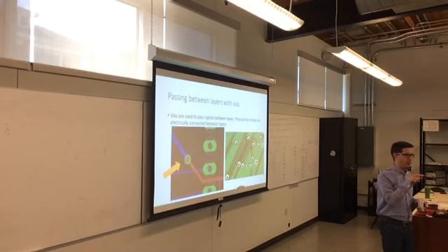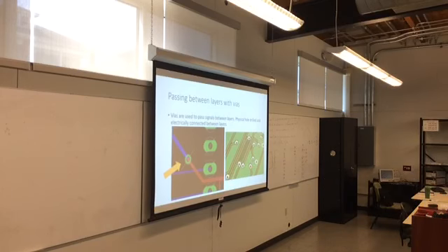Now, the PCB mill that we've got in the back, a nice nifty toy, will drill all the holes for you, but it will not automatically electrically plate them. So it is really just a drill, and they fill the hole with copper. That makes sure that the layers actually get connected. That machine can't do that. So we actually have little rivets that you pop, pop, pop into all the vias, and that's how it makes the electrical connection. I wonder if we have any vias on these boards.